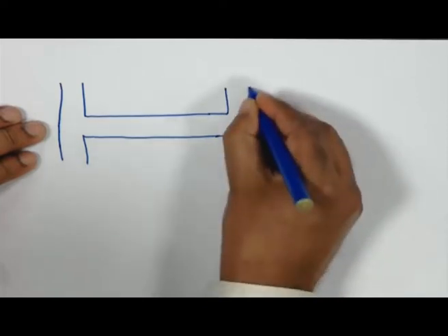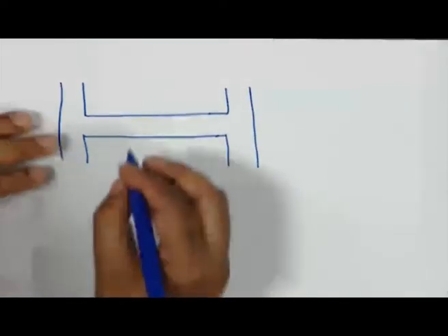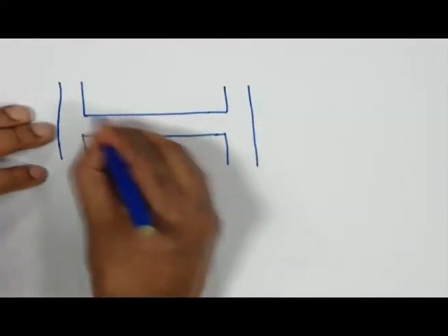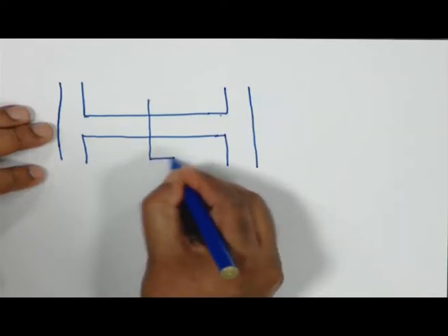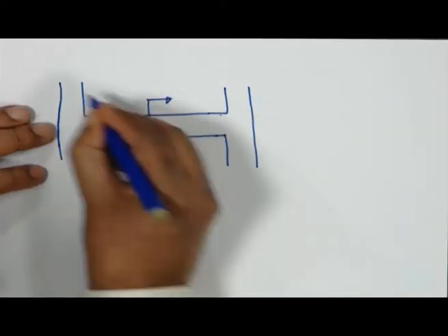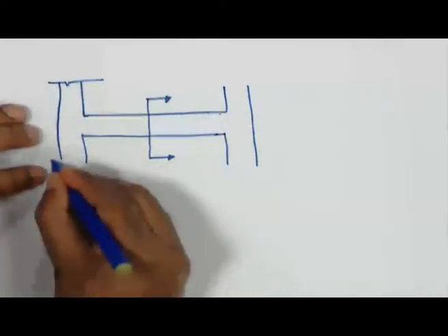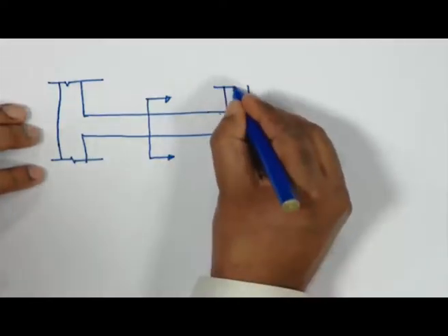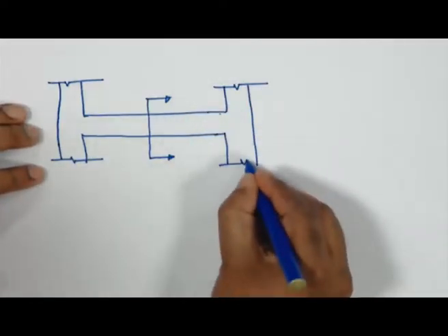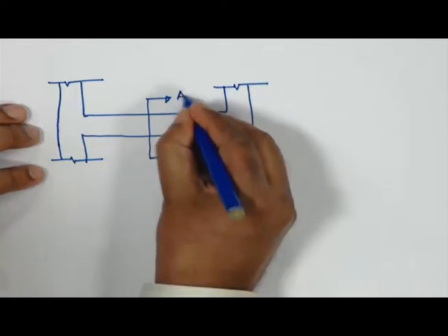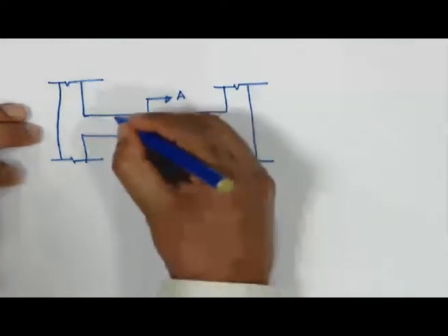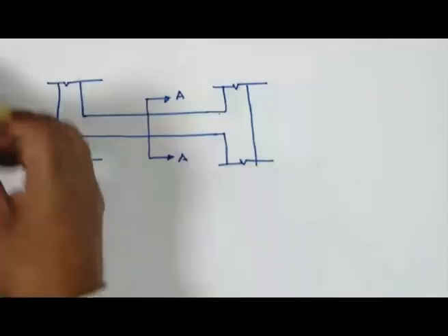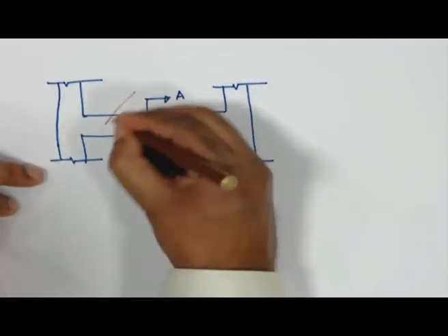Please note that the strain plane before and after will be linear, whereas the concrete has a certain portion that is parabolic. Here we are considering equilibrium of the beam. So what will happen? C should be equal to T, that is the equilibrium condition. And now we make a couple and find the bending moment.